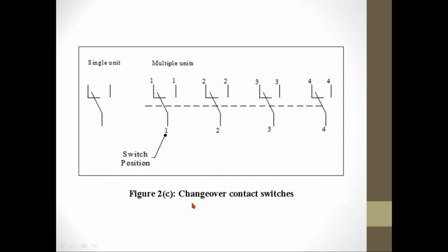So it is termed changeover because once it is triggered, for example, if you consider this point and this point, initially the switch provides normally closed contact, but once triggered, this point going to this point becomes normally open, or becomes open, and then this point here and this point will provide a close contact.